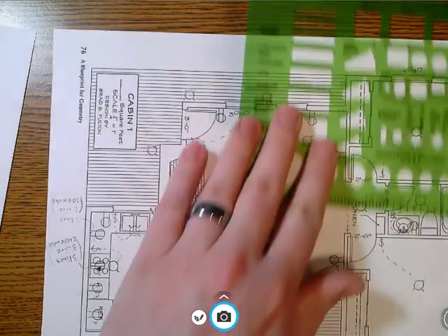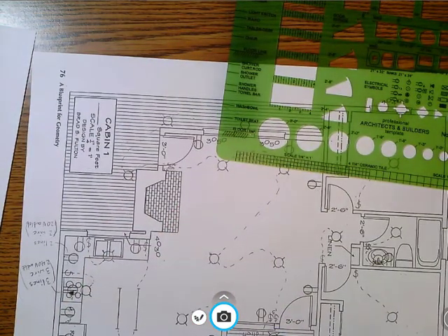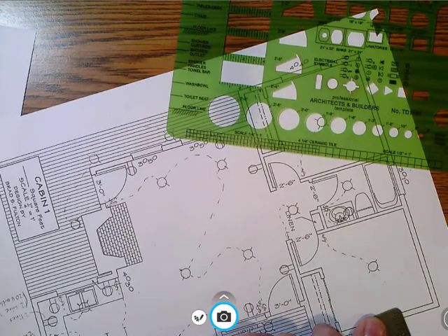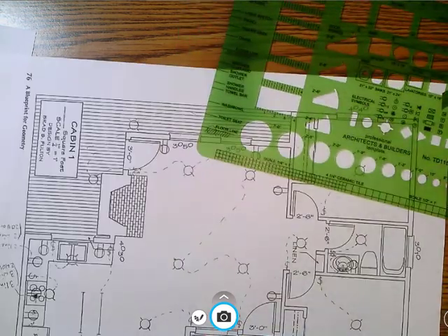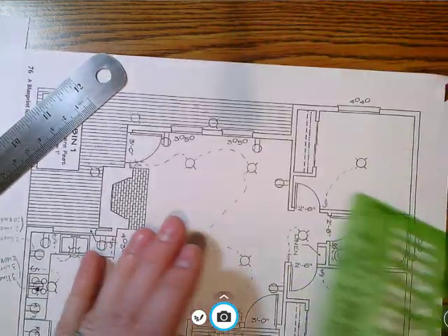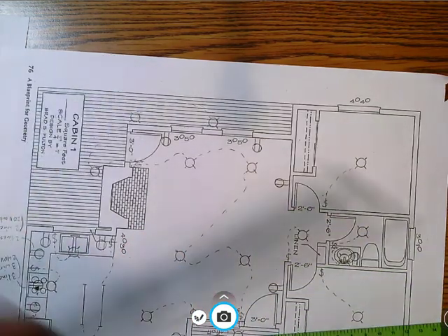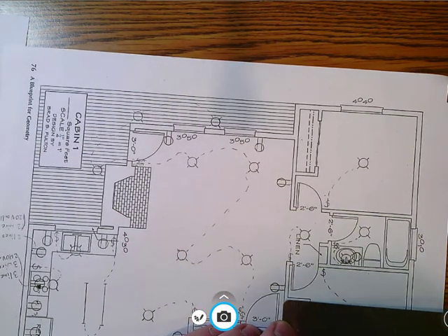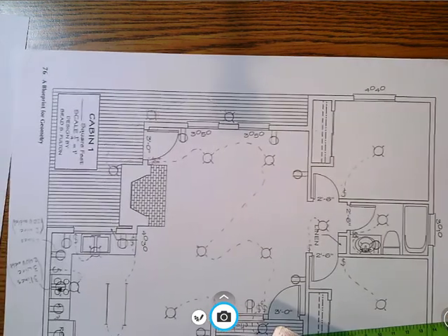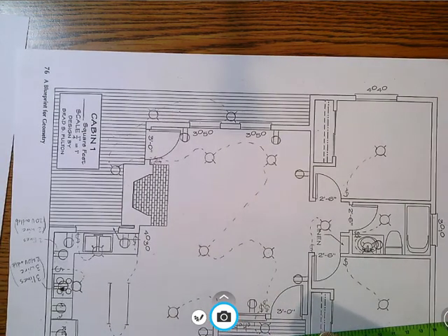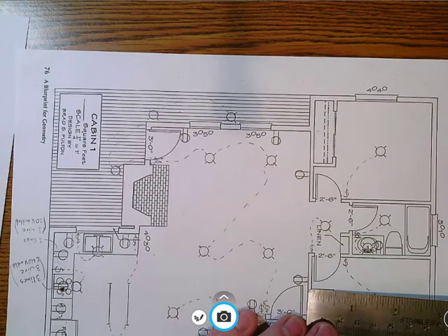And now let's do the bedrooms. What I am going to point out about the bedrooms is, once I measure the walls, 10 feet, less than 12 feet. Okay? So when I'm doing these, let's see, is this wall right at 2 feet? I believe an outlet does not need to be placed there. According to the code, it says at least 2 feet in length.